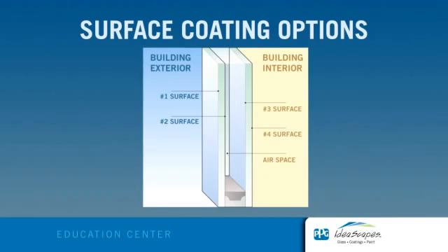In a standard double-pane IG, there are 4 potential coating surfaces to which they can be applied. The first surface faces outdoors and never has a low-E coating because of its exposure to the outside elements. The second and third surfaces face each other inside the IG and are separated by an airspace and an insulating spacer. The fourth surface faces directly indoors.